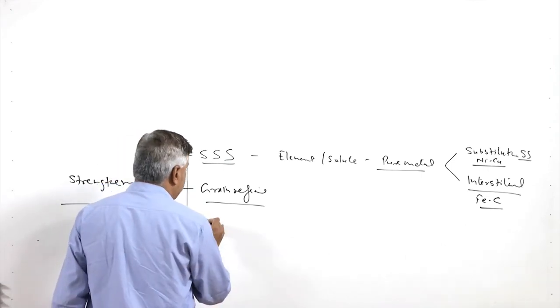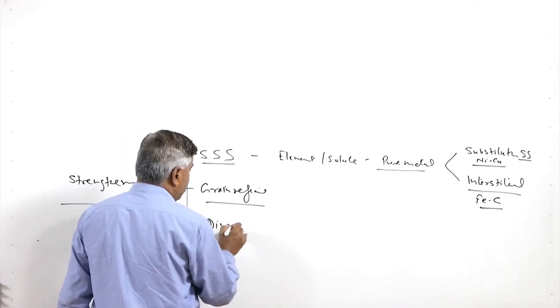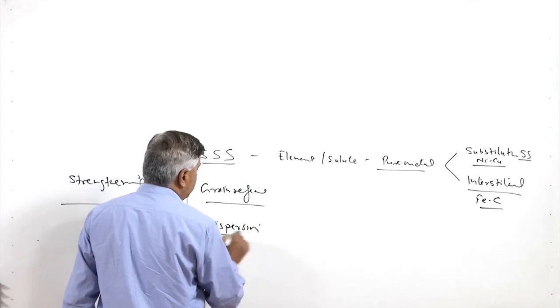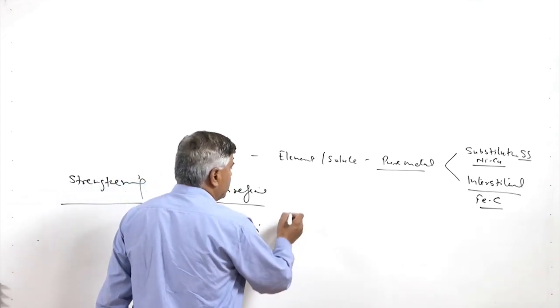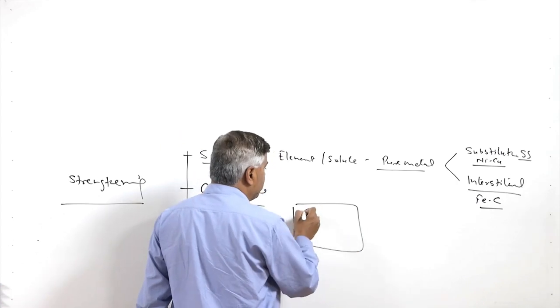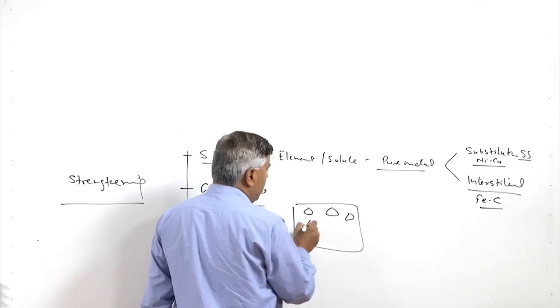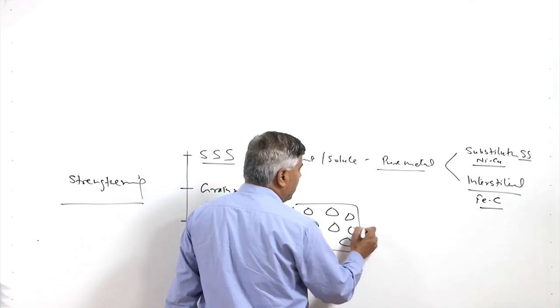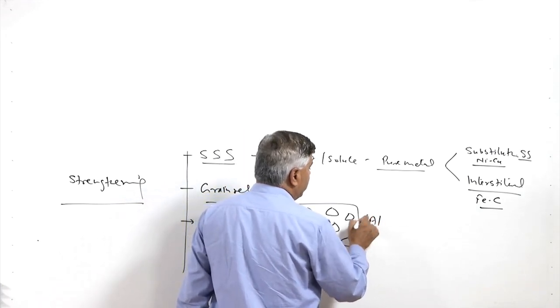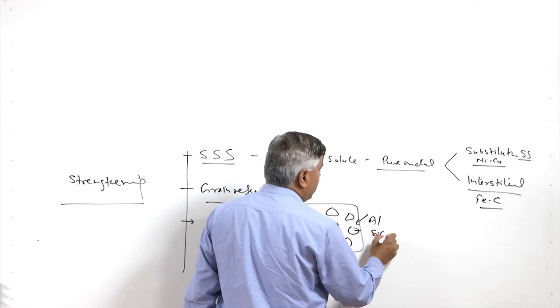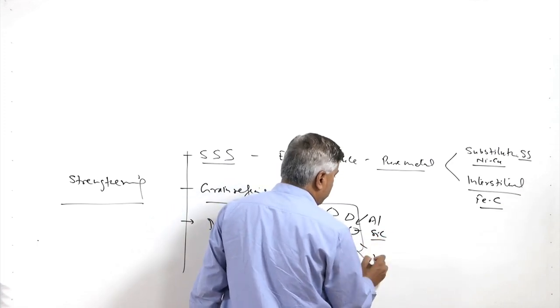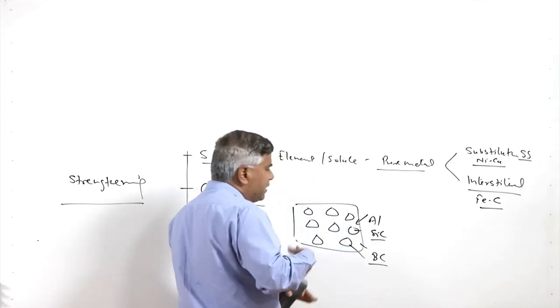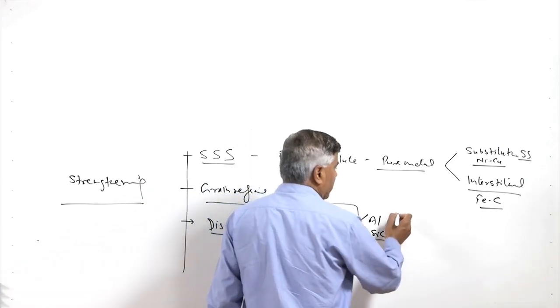Another is dispersion hardening. Dispersion hardening is used when the soft metal matrix is reinforced with hard constituents which provide support to the soft metal matrix. So, an aluminum matrix is fitted with high hardness silicon carbide or boron carbide. Such kinds of hard particles are reinforced,